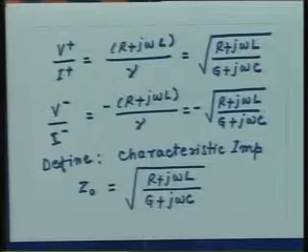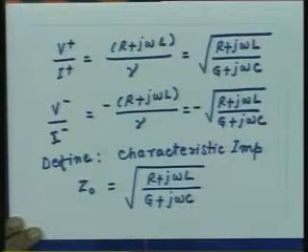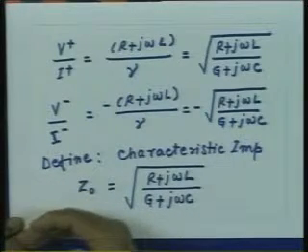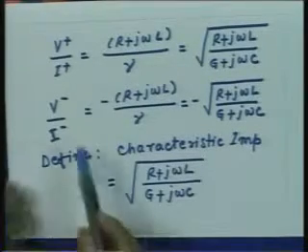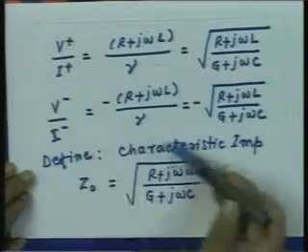And what does negative resistance represent? It tells you that the energy is not supplied, but rather energy is received. So, this essentially is telling you that if I look in the positive x direction, I will receive the energy, which makes sense in this case, because now the wave is travelling backwards, which essentially is carrying the energy backwards. Since we have an energy source at the left, it is equivalent to saying that there is something on the right side which is supplying energy to the energy source on the left side. So, the backward wave is like an energy source supplying energy to the generator, that is equivalent to a negative resistance. So, here negative resistance is not in the conventional sense, it is a manifestation of the direction of the energy flow on the transmission line.